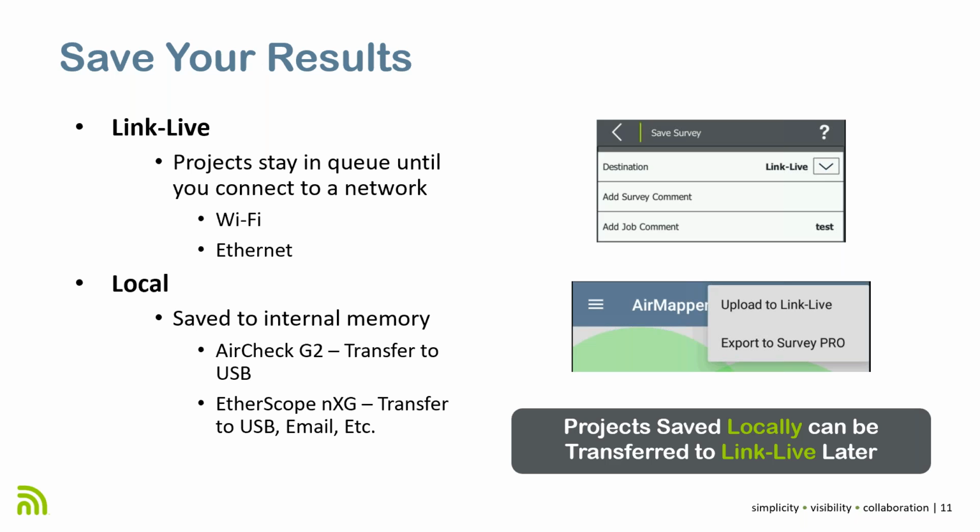Notice one tip, and this was recently, really, a couple of weeks ago. Initially, if you saved an AirMapper project locally, you had no way of uploading it to Link Live. So maybe you changed your mind. You were like, okay, let me save it locally. And then you're like, well, I want to try and use Link Live. And there was no option to upload a local file to Link Live.